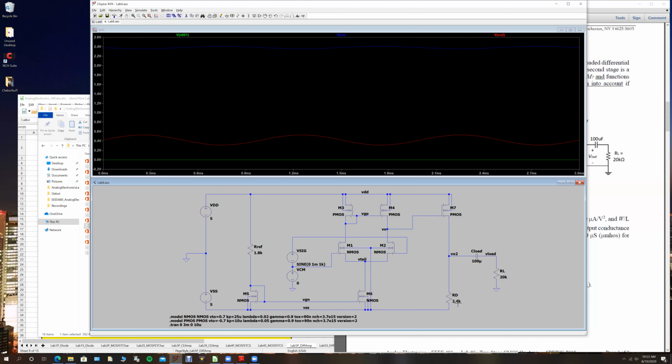Maybe you'd have to decrease that voltage. Lowering this resistance maybe to 2.3K would have gotten us closer to 0 volts. But 2.3K is not a standard value, and so you wouldn't be able to construct that with a single resistor. You could with series and parallel components, but with just a single resistor, 2.4K is probably as good as you're going to get.